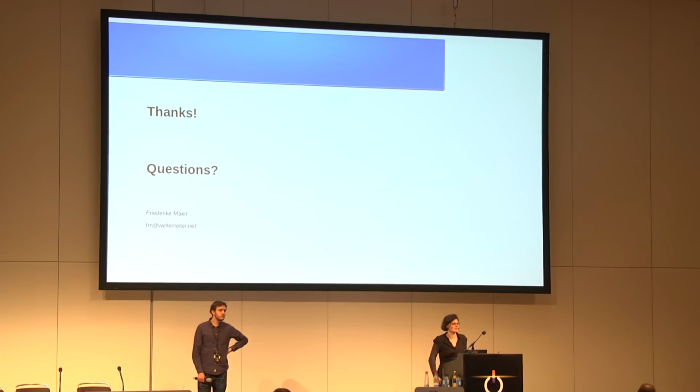Is it always the case that I need one receiver per part of the antenna? You need some kind of construction that does the directivity. You don't need an antenna array; there are also other forms of antennas which are directional. But within the array, you need different signals to get these different phases to create your directivity.